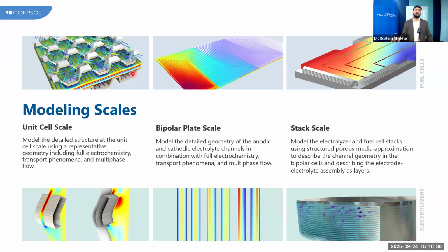So here we already have these three layers available. Now additionally, these bipolar plates are deployed there. These bipolar plates will give you the flow arrangement, and because of the flow arrangement, the fuel provided to the cell may be varying. If the fuel provided to the cell is not sufficient, or not uniform, then we will see non-uniform utilization of the fuel, and that may create some local problems.